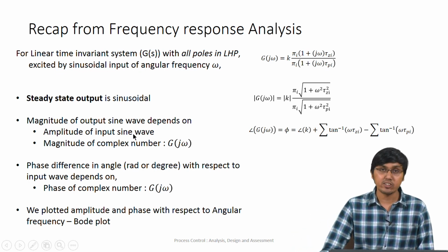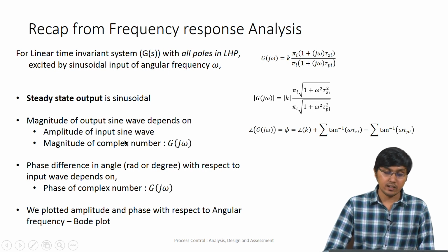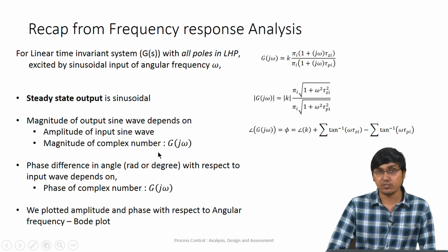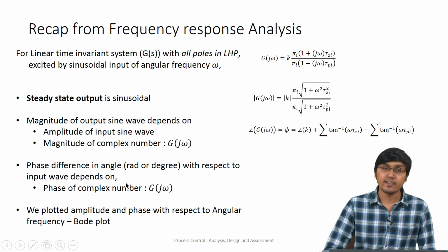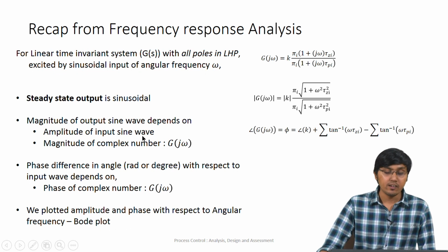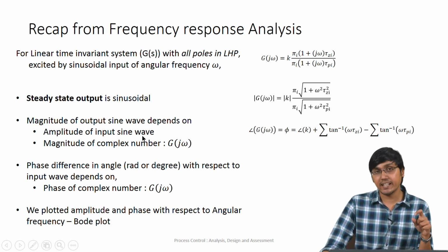The magnitude of the output depends upon the amplitude of the input and also the magnitude of a complex number G of j omega, where G of s is the system. There is also a phase lag that we observed in the output. So we had the magnitude change and also the phase change.